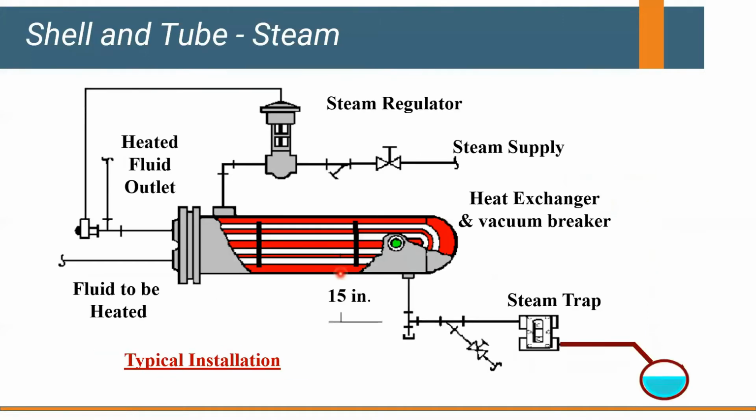You would always want your condensate going to some type of gravity drain. And if you have to lift it, it's a really good spot to put a little condensate return unit and pump it. But don't use the incoming steam pressure to lift condensate. Now we're going to do a steam class later in our series. We'll touch more on this, but just a quick example of why you don't want to lift condensate off of a shell and tube heat exchanger. Any heat exchanger for that matter. You'll tear it up.